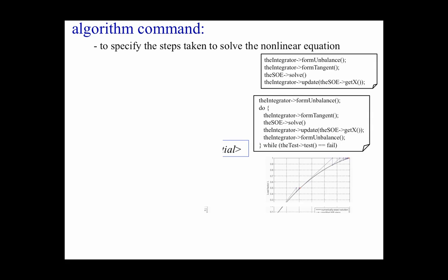So I'm just showing here the convergence of a regular Newton algorithm and a modified Newton algorithm. With regular Newton, you should converge faster than the modified Newton. The regular Newton is using the current tangent at every solution step to get to the solution. So hopefully we'll get there in 4. The modified Newton is using that initial tangent at the start of the step.